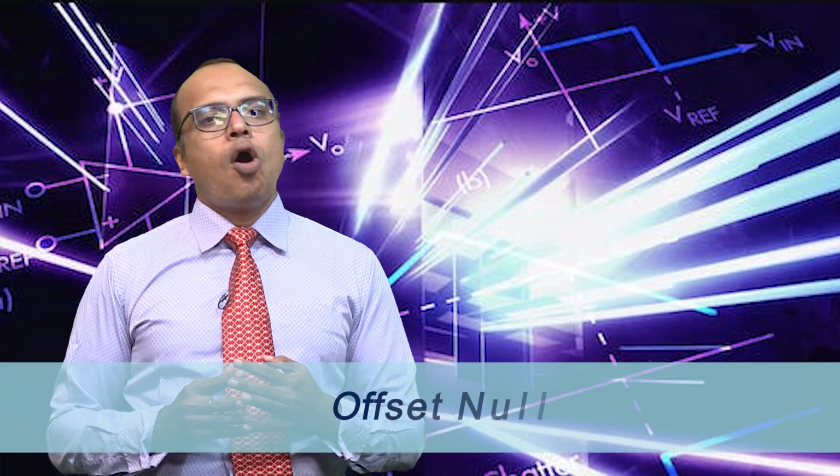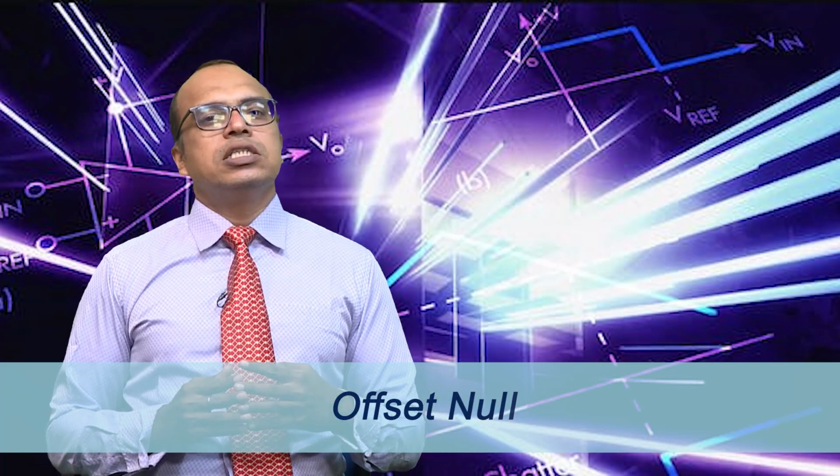Compensation and frequency compensation. Some op-amps may include an internal compensation circuit to stabilize their performance, especially in high frequency applications. This compensation is designed to prevent instability and oscillation. Offset null. Many op-amps feature an offset null adjustment, which allows you to fine tune the output voltage to 0 when there is no input differential voltage.